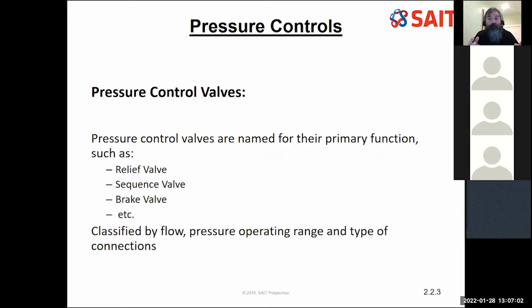I'm going to call it a brake valve, even though it's exactly the same valve. So don't be surprised when you see a symbol and a name associated with it, and it's got a different name than you've seen before. Remember, this whole system wasn't really designed by engineers. It was designed by mechanics and millwrights, and the naming convention is basically based on what we're using that valve for. Okay, so a relief valve, we're going to relieve the pressure in the system.